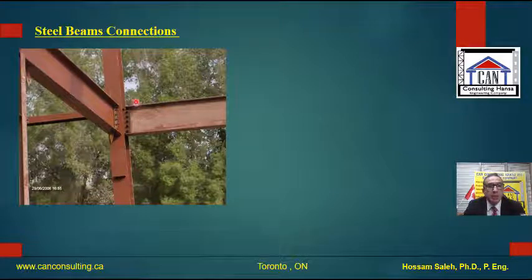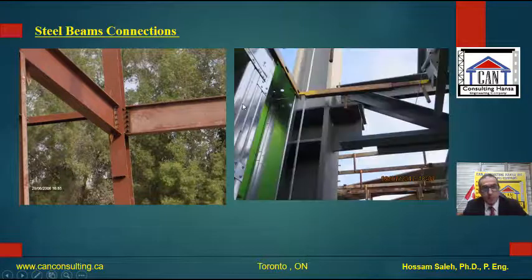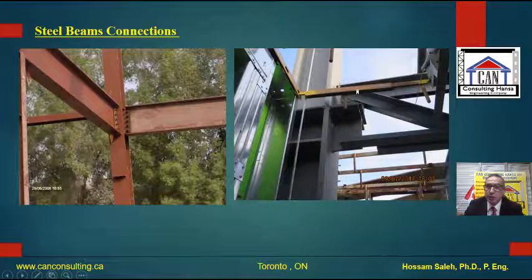So you can have more than 12 or 14 meters high steel column, and then at each floor you can have a gusset plate and the connection to that. And as you can see, the steel column is straight, and here you have a small corbel or bracket, and that's where an open web steel joist or a girder sits, and then you can have the girder connected to the steel column.